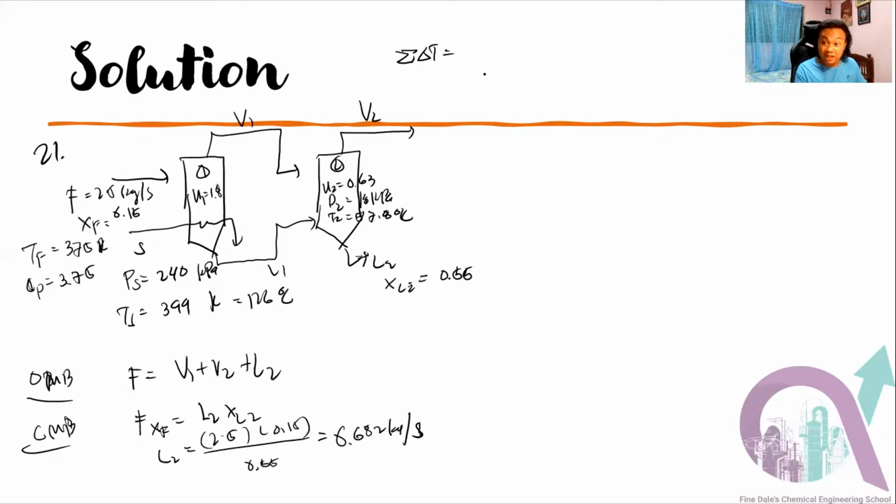Okay, so you now get the overall temperature difference. We have 126, which is 399 K, the temperature of the steam. And also you have 57.8 minus the 6 BPR. You have 62.33 Kelvin or degrees Celsius. They are the same because it's delta T, it doesn't matter.